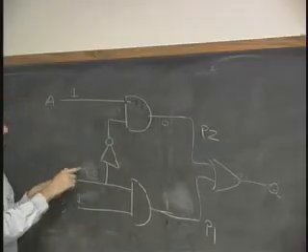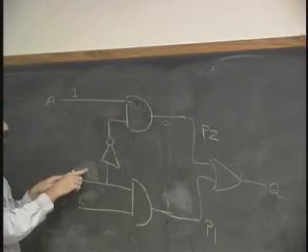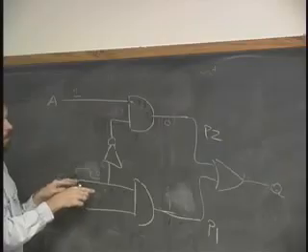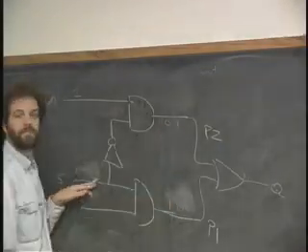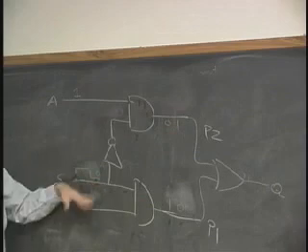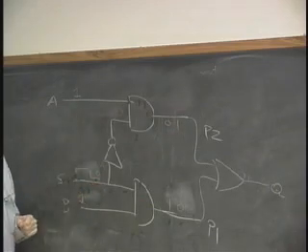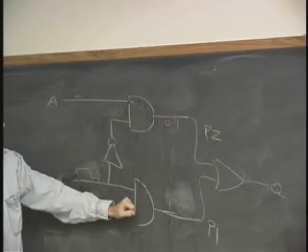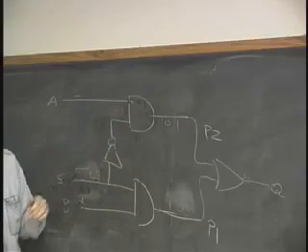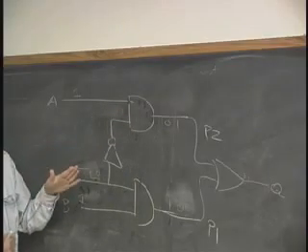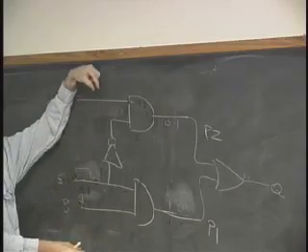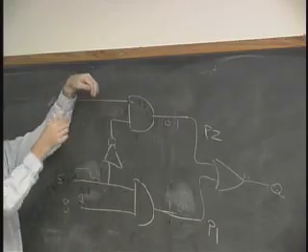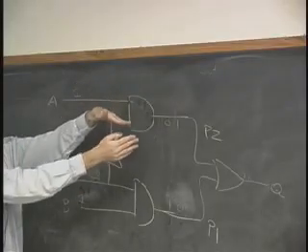And then I'm going to switch S. I'm not going to change these guys. I'm going to drop this one down, which will turn this one off and turn this one on, right? Basically, I'll be saying, okay, stop letting B through and start letting A through. There's 2 gates, and I'm questioning which one is going to be open. Think of the selector as being made up of a whole bunch of gates, each one gating each of the inputs to say which one gets to race to the output.